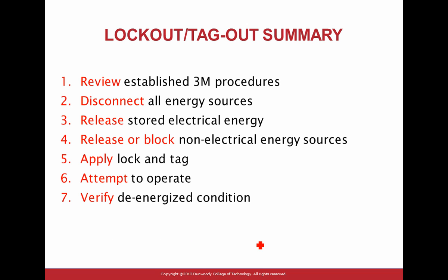Okay, so the rule is de-energize and put the equipment in a safe working condition. To do that, there's a process that you guys follow. Number one is to review established procedures for that piece of equipment. I assume you guys are familiar with that one. But 70E goes through the following. If I have a machine I want to shut down, the first thing is you have to turn the machine off.